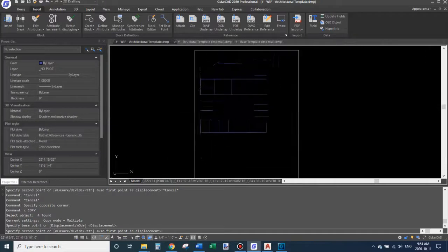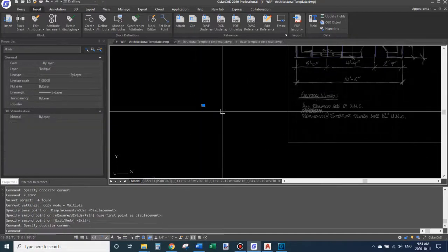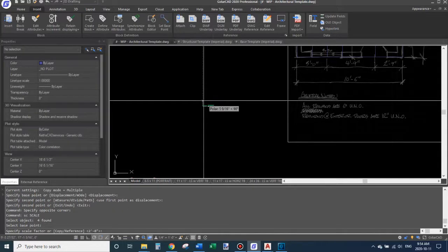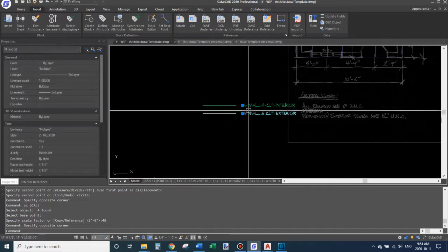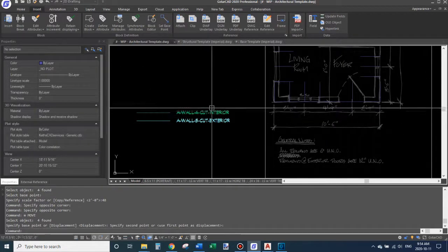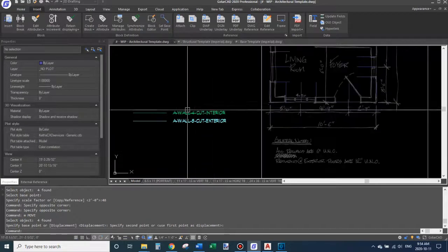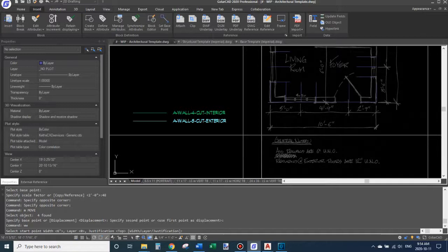wall layer later on. So with AutoLisp, if I'm always using these 2 layers to draw my walls, or just a select few layers, I can build those options into my Lisp routine. I'm not trapped using these 2, having to type the whole layer name. I'm going to show you what I'm talking about in just a second here. So I have the option to choose the layer.